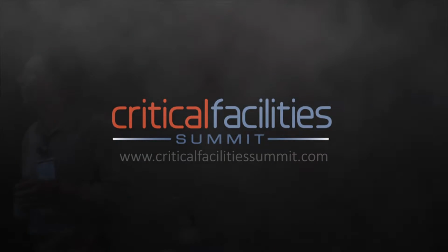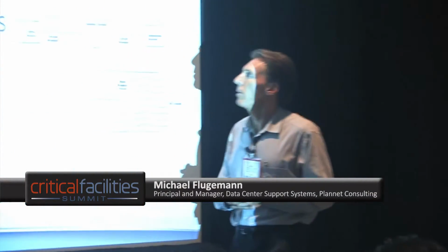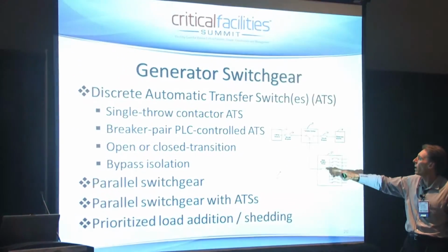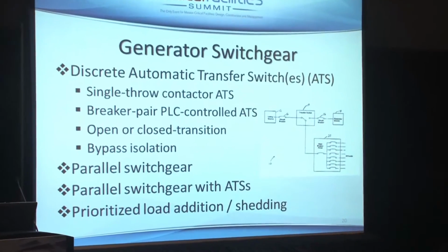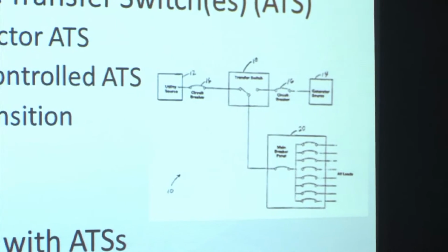So with automatic transfer switches, this is a key part certainly to generator power. Just a typical basic ATS that switches from utility power to generator power and feeds the load. Critical facility, usually cooling, and UPS, and in some cases an operations center.